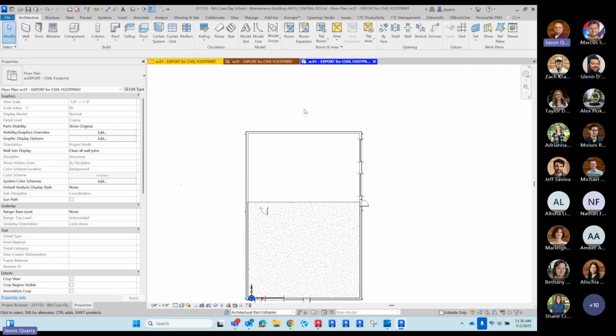I think Shane and I have been kind of messing with some CAD DWG export settings for EFIC. They have specific requirements that they need. They want their walls to not be A-wall. They want it to be A-wall-PH for partial height. We're not really sure why. But some jurisdictions do have those kind of limits that they place on you.